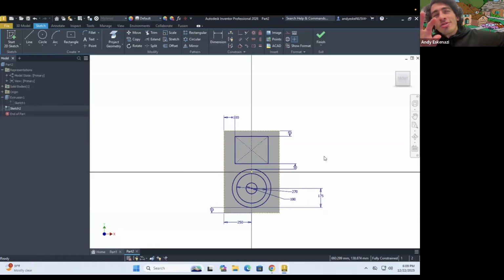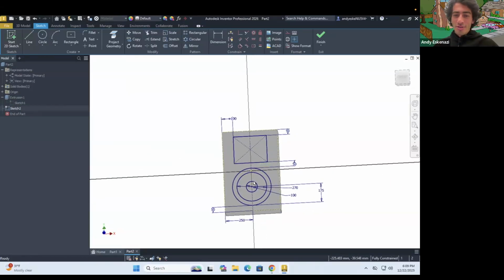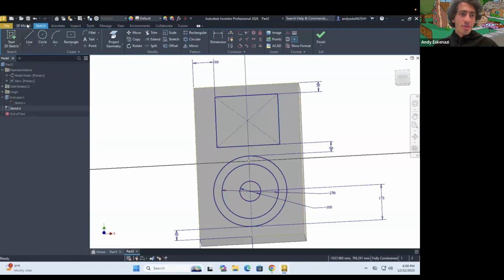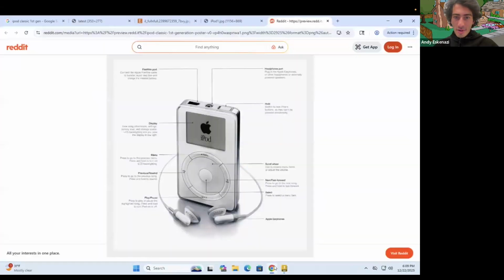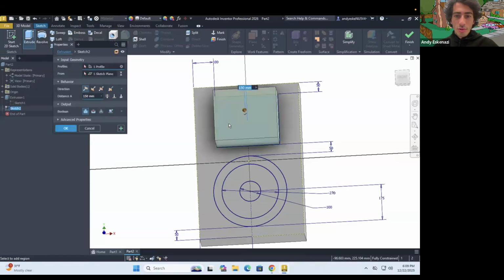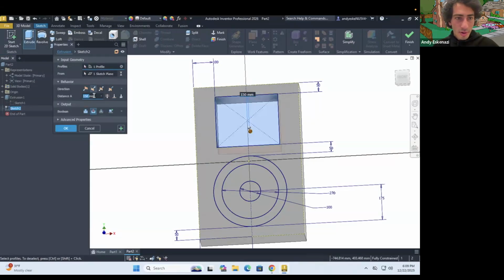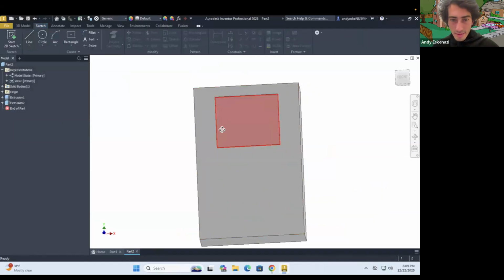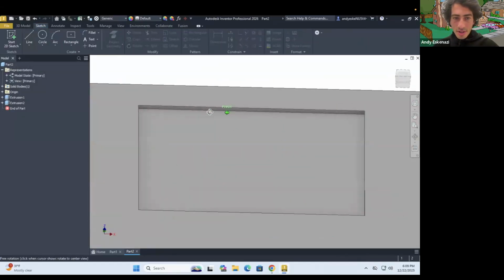So again, much easier techniques than this one. Or actually, there's gonna be more techniques that we're gonna see in the future to make this look prettier than the model I'm showing you right now. But this ain't too bad, and you will see why in just a moment. But all right, so suppose that we have that. So I'm gonna go to 3D model, and if we go here, see there's like a slight recess, right? So what we'll do is go here to extrude. I'm gonna go down, and we'll go down by 5, but just that amount.